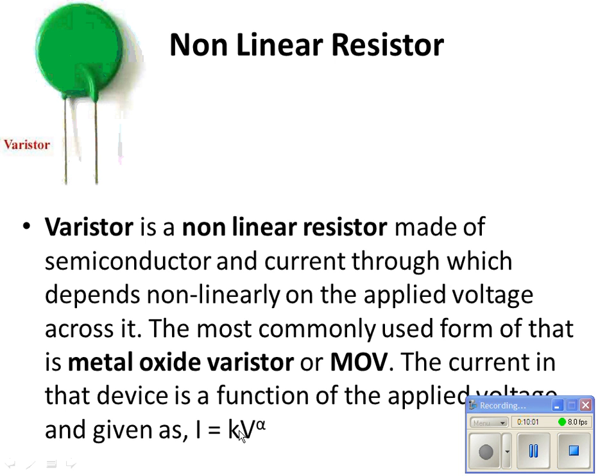If you have a blue receptacle at your office, that means that it has MOVs in it, and if you get a spike coming in from Edison, the MOVs will eat the spike, but it also tears away part of the MOV, literally. It destroys the MOV as it goes, but the spike doesn't come through the receptacle.